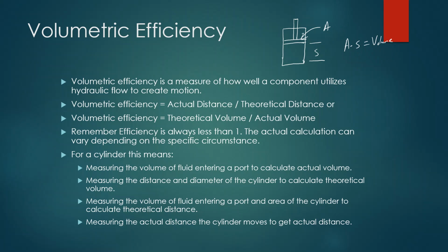Another way of looking at it is area times height, right? If our volume of fluid that we put in doesn't create the distance that we expect that the cylinder will move, then what happened? Well, the fluid didn't just disappear. What happened is it leaked around the seals.